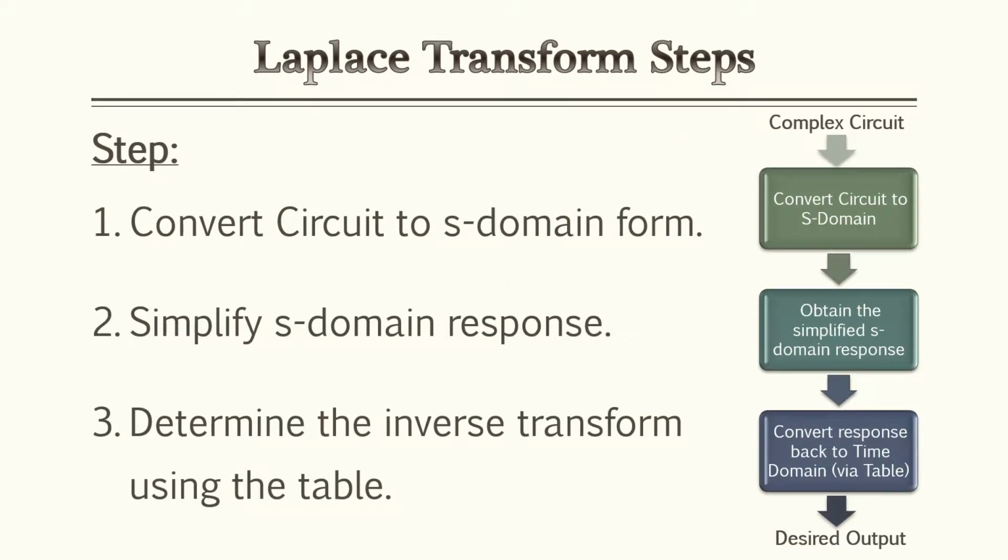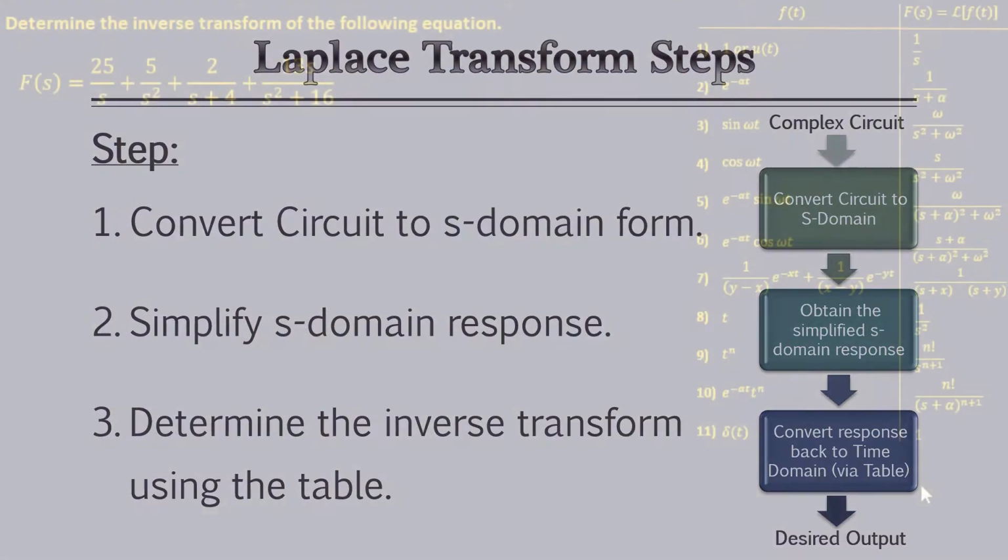Now just an overview of the steps before we get into exam problems, the Laplace transform steps. First thing you want to do is convert the circuit to the S domain. Simplify the S domain response. In other words, you're going to simplify the big equation down to as small as possible. Then you're going to determine the inverse transform using the table. So this is where you take that S domain response and you refer to that Laplace transform table to revert back to the time domain. And again, we're going to go over this in the exam problems next.